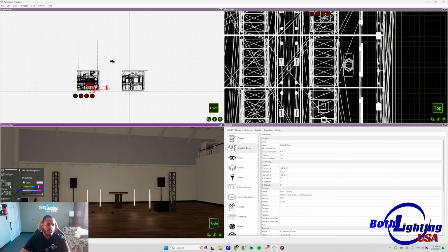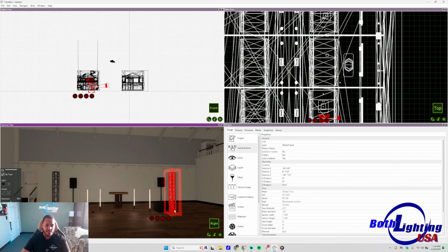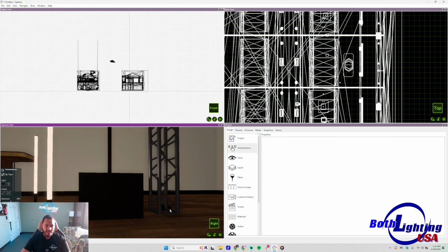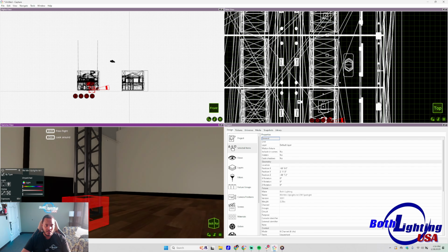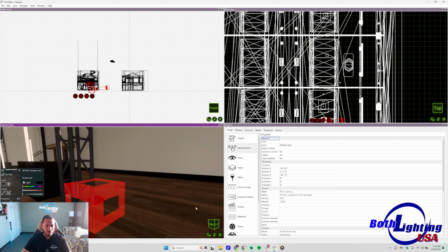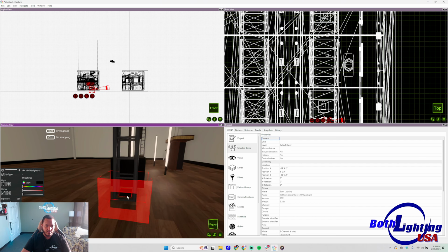And let's go ahead and turn the uplights on in the totem, because now we can see our uplight is facing upside down. So we want to go ahead and rotate that as well. Negative 180 degrees will get our uplight facing upward. So I'm going to try to click on that other uplight over here. May need to zoom in. You can see it wasn't exactly in that totem. I'm just going to move over a little bit, try to get it exactly in that totem there.